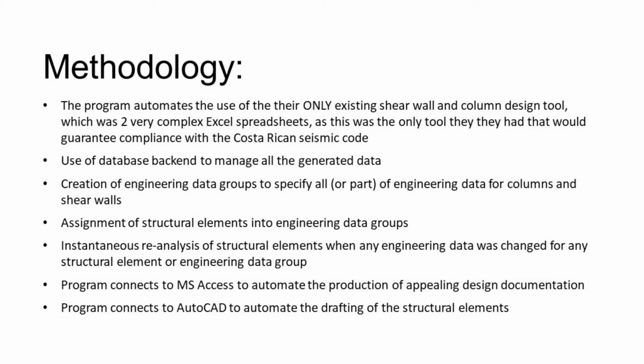The program does what a human would do to use the spreadsheets. It enters all the engineering data inputs into the cells and then interprets and displays the analysis results from various output cells, which previously required a human to interpret using various unwritten rules, like comparing two different output cells, or looking at a graph to see if various internal force states appeared within an area on a flexocompression diagram, or if a particular cell was above a certain value.